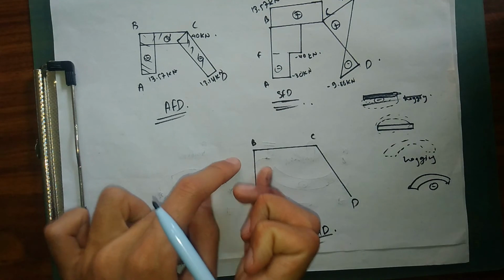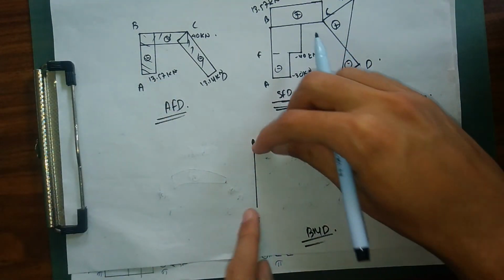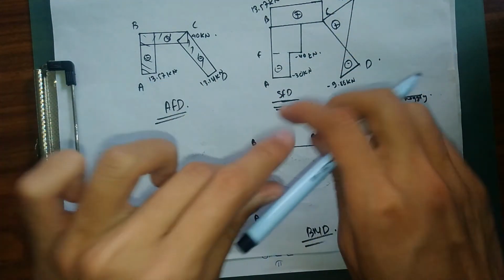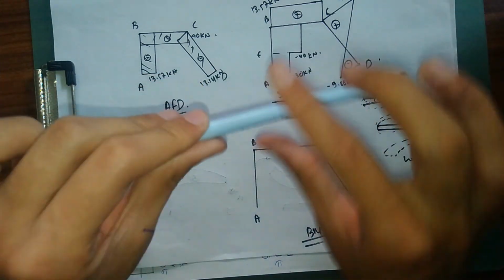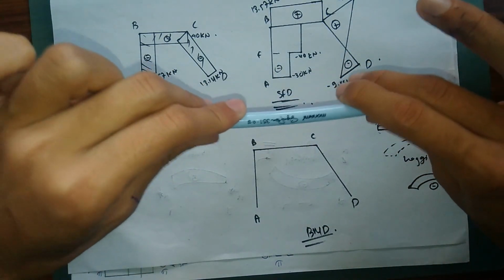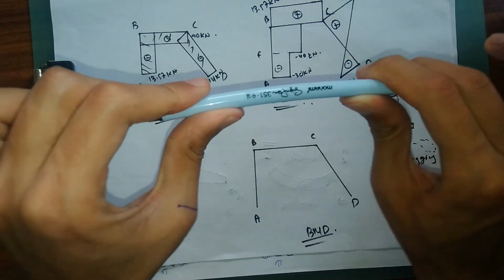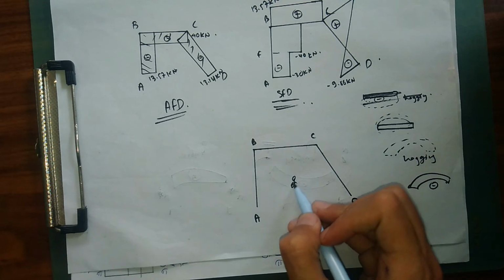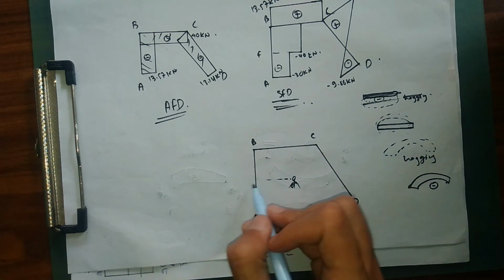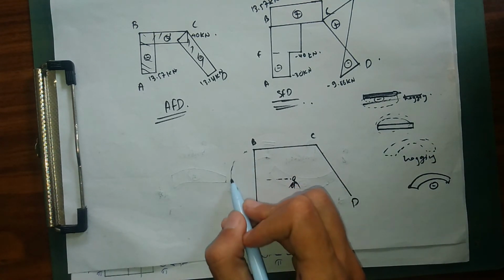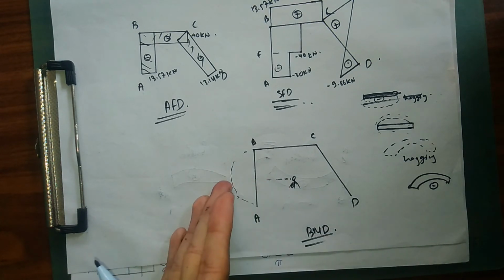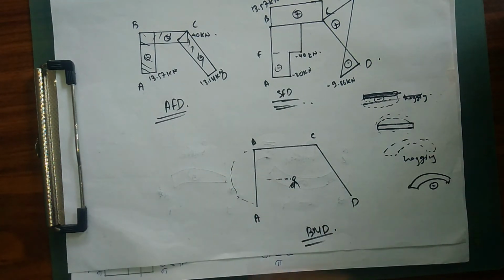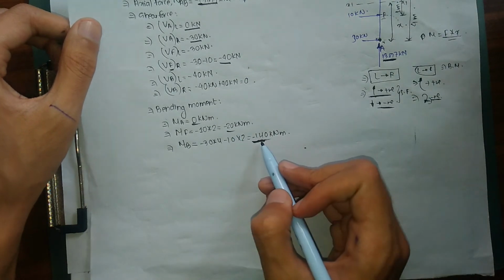So if this is my beam, and it is negative, which means it needs to move upward, it needs to move in this way. This is hogging, as you can see here. This is sagging, which is positive, but right now we have hogging, which is negative, which means upward. So this is my upward direction. If I am observing this beam, hogging means it is moving upward in this direction. So I'm going to show my direction of bending moment this way. You can show your bending moment downward as well, but in actual we need to show it upward. So right now I have my bending moment of 0, minus 20, minus 140.